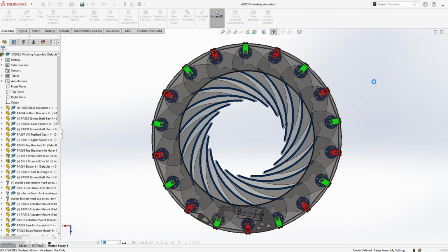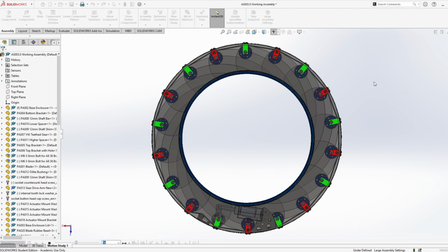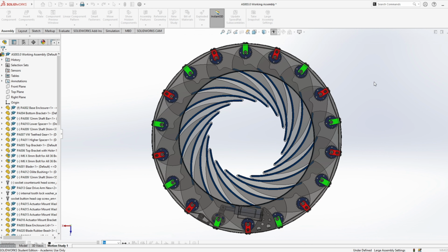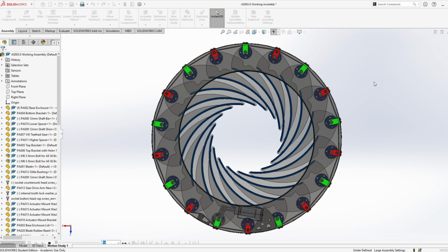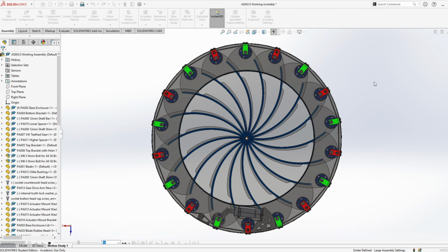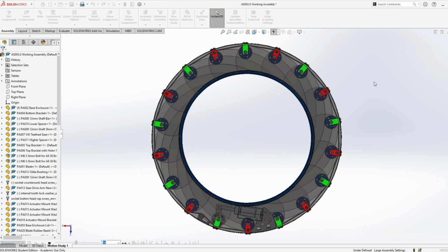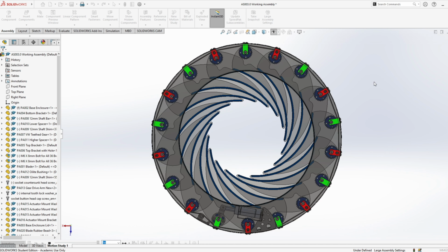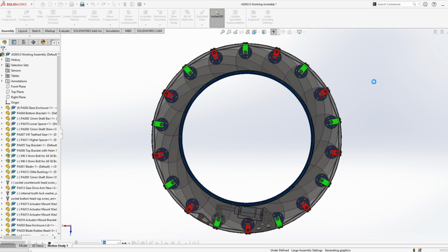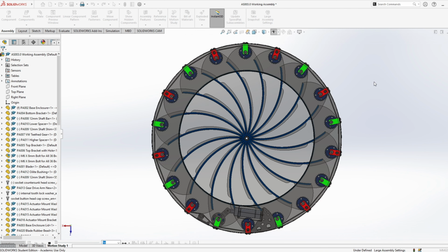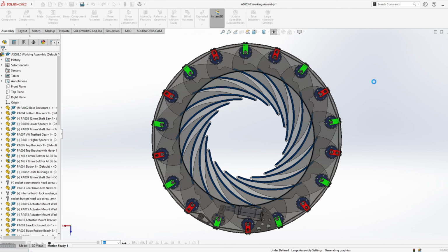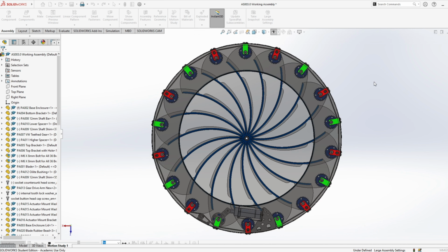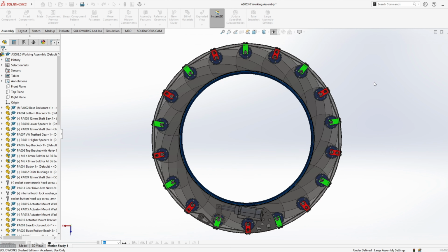So, this earlier prototype was designed around a single-sided HTD timing belt at 2,800mm long. So the width of the belt was 20mm and the pitch between the teeth was 8mm, where both the belt width and the pitch have stayed the same in prototype 2. The major difference in prototype 2 is the overall length of the belt, which has increased significantly to over 3 meters. So I think it's approximately 300mm longer or 350mm longer. I will talk about that later.